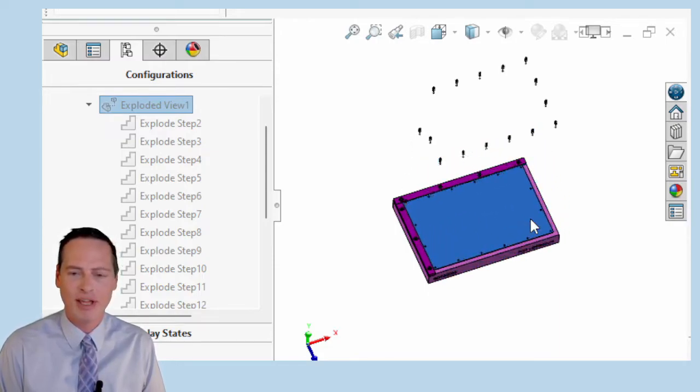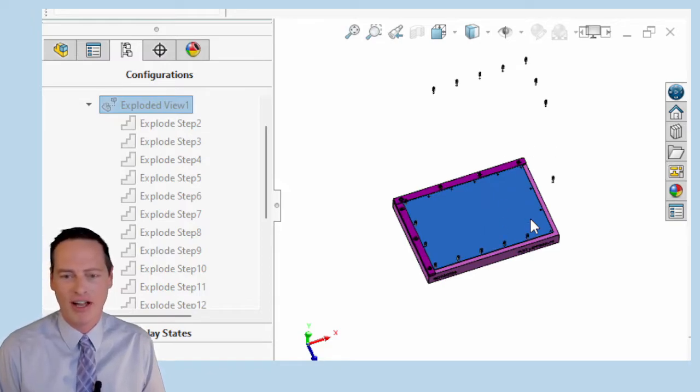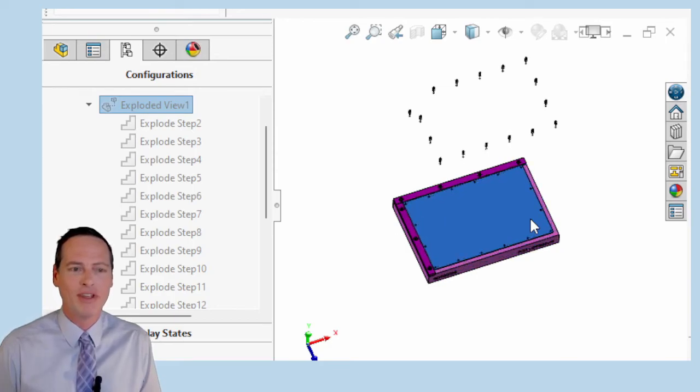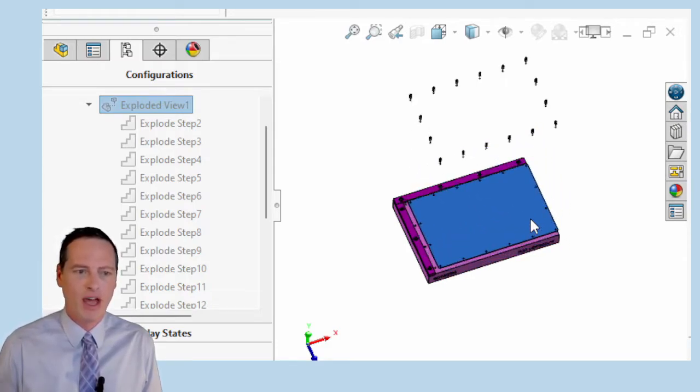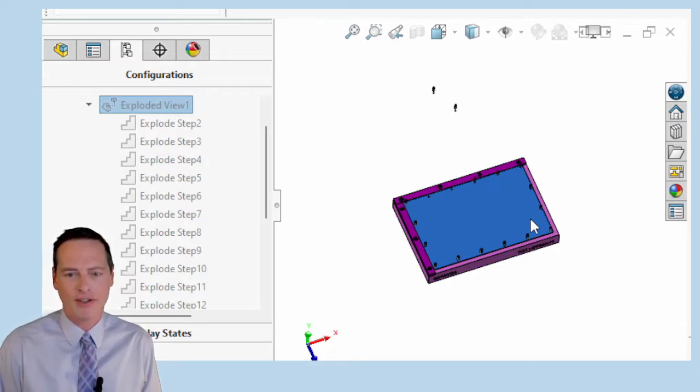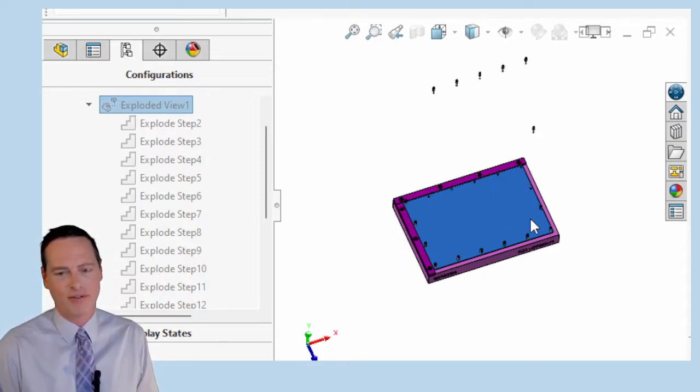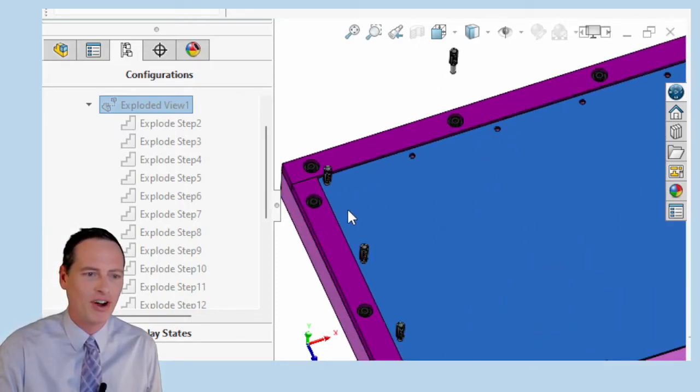When you put it down onto the datum A simulator, it's going to make a lot of contact. If this is a thicker, stiffer part, it would only make 3 points of contact, and it would constrain 3 degrees of freedom. Then when you slide the part up against the datum B simulator, it will make 2 points of contact and constrain 2 degrees of freedom. Then you slide it over to the datum C simulator, make 1 point of contact, and constrain the final 6th degree of freedom.